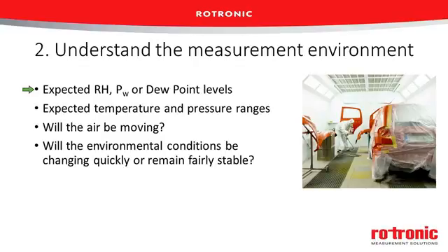Also, pressure ranges. You should understand the pressure variations. And I'm not talking about barometric pressure. Most instruments cover the full range. But I'm talking about pressurized vessels or compressed air systems. You have to worry about the actual sensor performance, and you have to be concerned with the placement of the probe into the pressure. And that goes to what type of fitting you'll need, or will the fitting even match? So you want to know what kind of pressure situation and how much the pressure will be.